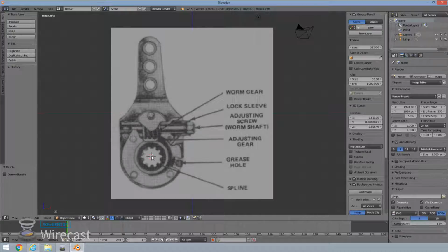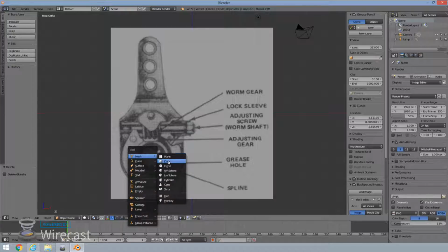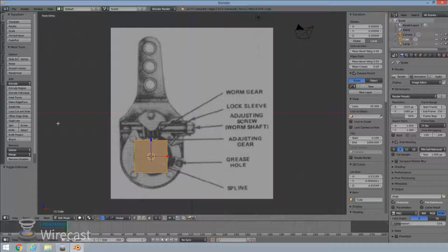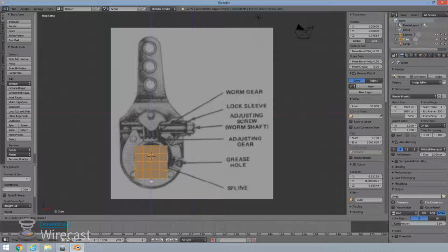So I'll start my center roughly around here. I'm going to hit Shift A to bring up this panel, where we'll find our cube. Select cube, go right away into edit mode, and I'm gonna right away subdivide it a couple of times. This is good enough. I'm gonna bring it down a little bit, so hit G and Z, so we have it down there roughly.